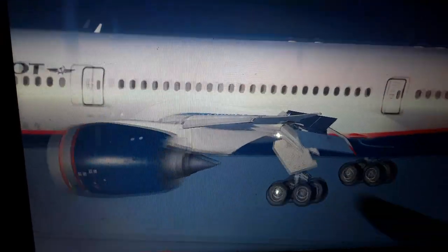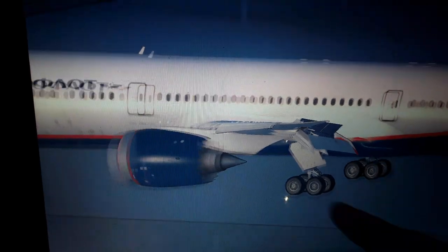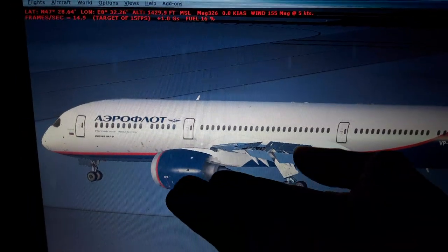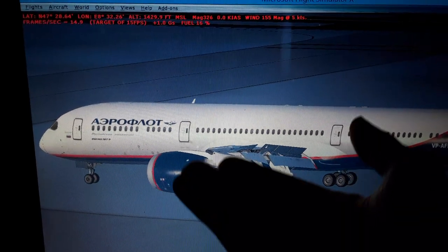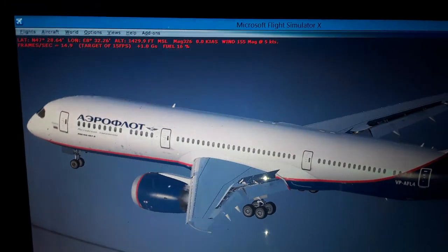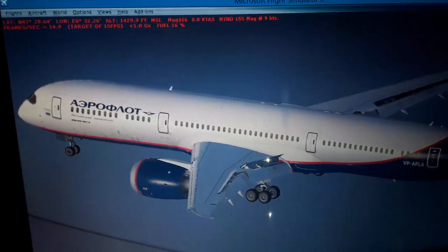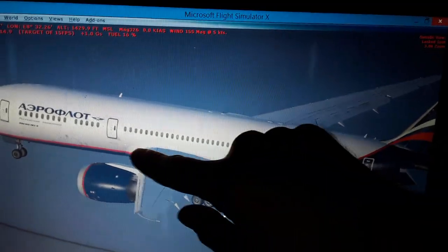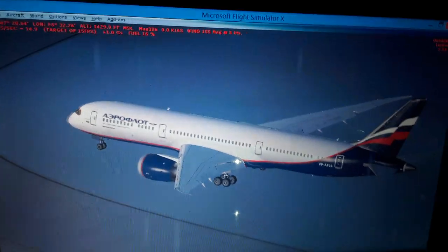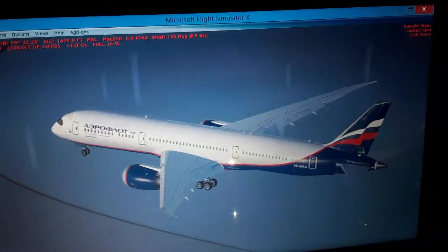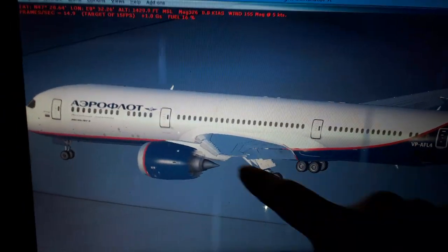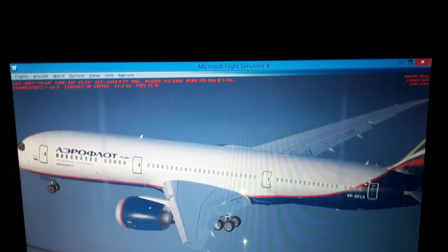And also because we have the curvature from the flaps, the airflow is moving slower below the wing. So we have higher pressure below the wings, which pushes the aircraft weight and wings up into the air. Also, you can see the top surface of the wings is more curved, so as the aircraft accelerates for takeoff, there is lower pressure above the wings, which sucks the aircraft up into the air, weight and wings and all. So we have differential pressure between the lower wing surface and the top surface as we fly.